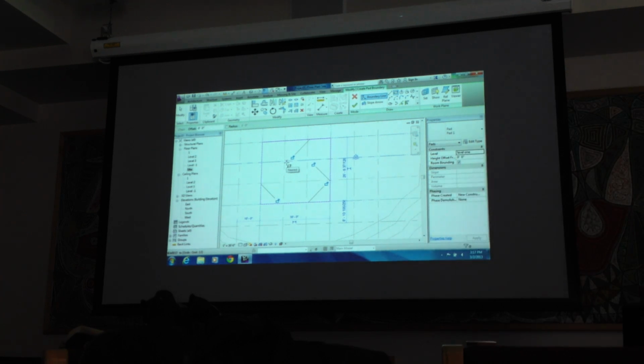And then, as you see, you could notice how there's the lock icons along on the screen. How that works is, if you don't want the building to change at all, you click the lock icon and it'll lock the highlighted area to the grid line that you just created.